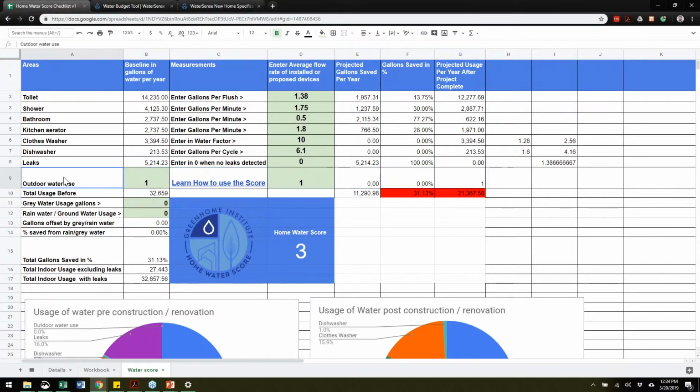So when you're using the outdoor water budget tool, basically it's going to tell you your site should have been using 3,000 gallons of water for the year. But with your great plan, you're going to be using drought tolerant grasses that work just like Kentucky bluegrass but don't have to be watered at all, and you're going to be using rain gardens, reducing your landscaping and keeping the rest of it native. That's what you're going to do, right?